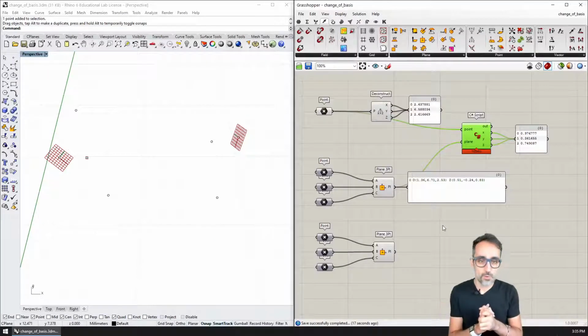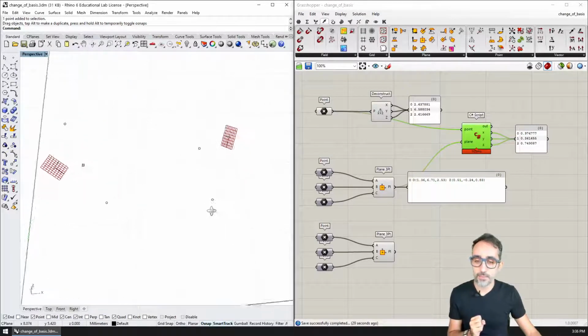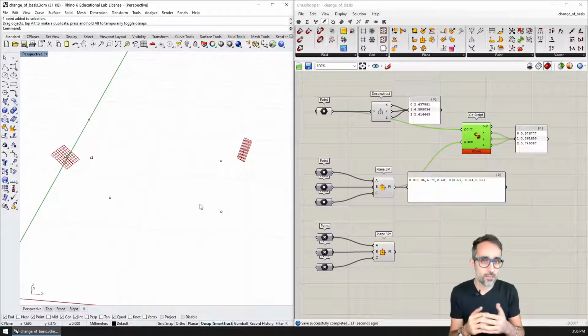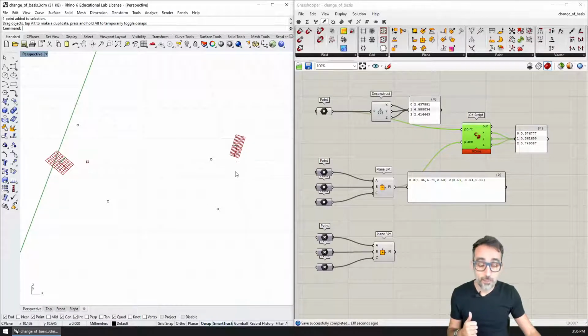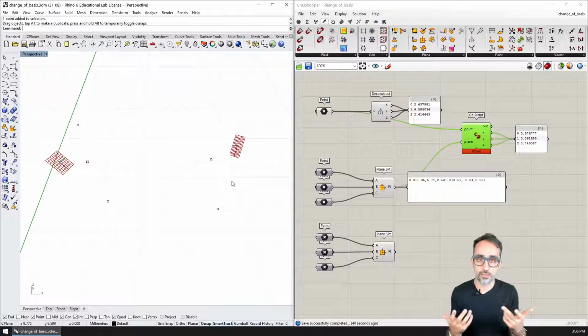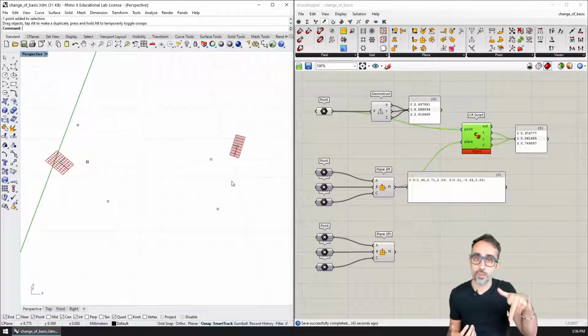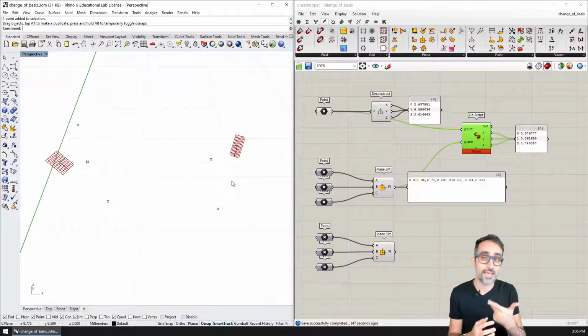All right, so let's get started. We're going to be implementing this in C# for Grasshopper, which is a procedural modeling environment that is a plugin for Rhino. But this process applies to any framework that has some kind of geometry kernel. Grasshopper happens to have plane objects, a structure that contains three orthonormal unit vectors x, y, z, representing the orientation, and a point that represents the origin of that plane.